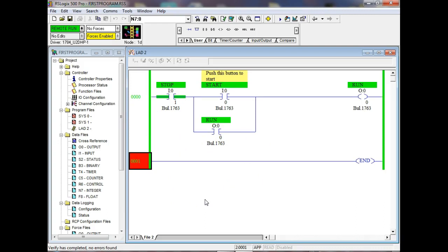So what we're going to do right now is, this is what we call the stop button. Okay, so right now I've got it true. Then I'm going to come up here and just touch the start button. Can you see what it did? So the light up here should be on for output 0. And then whatever I had connected on that guy would be energized, right, or it'd be running or whatever it's hooked up to this output. And this guy would run forever until we do what? Turn off the power.